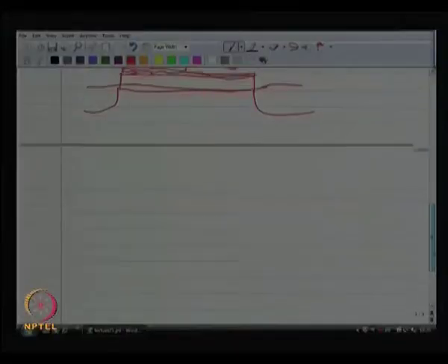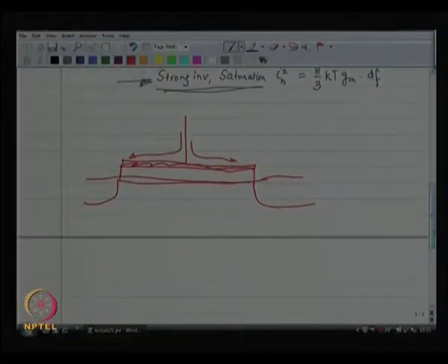Now, whenever you have a resistance, you can think of electrons jiggling around because of temperature, and when they are jiggling around because of temperature and there is resistance, it is going to cause a voltage, right. So, therefore, the gate has some random noise voltage on it.